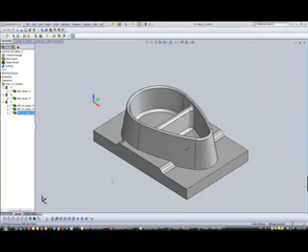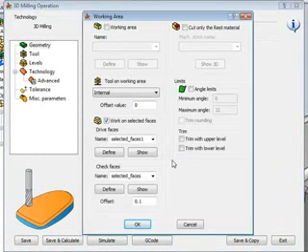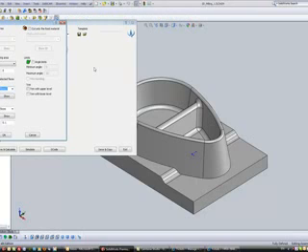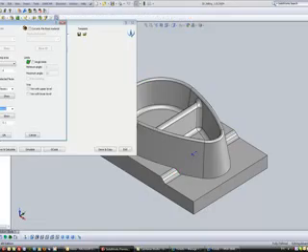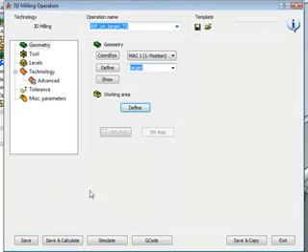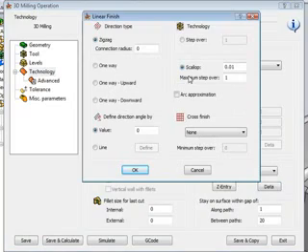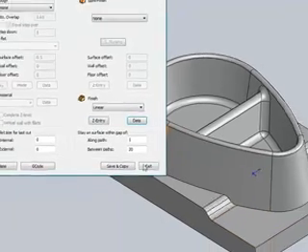Now, in my next operation, I'd like to do a finish cut of linear just on these outside floors over here. So if I go into my operation, again, we're using the target, and in my working areas, I've switched my drive faces and my check faces. Now my drive face is the floor over here, which was before the check faces, and my check faces is just the opposite. This area around here, also staying 0.1 millimeters away. In the technology area, we'll be using linear, and in my data area, we'll have a scallop of 0.01 to give a really nice, smooth finish on the part itself.